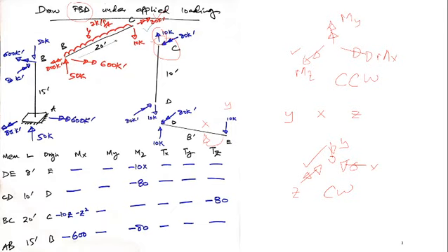This member is also in Z direction, so this is actually a torsion. So this would be balanced here. That would be balanced here, 80 kip foot. That is easily transferred as it is. And finally, I have calculated this 600 kip foot.